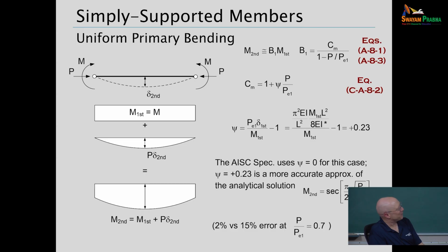In design practice, have any of you ever designed a member in uniform bending? Would the end conditions be pinned? Probably the closest to this case might be if you have a strut, maybe a WT section or something like that attached to gusset plates, and you're delivering the compression through the gusset plate. The gusset plate doesn't have much flexural stiffness compared to the members, so maybe you're getting close to a pin there. But even in that case, you're getting some restraint.